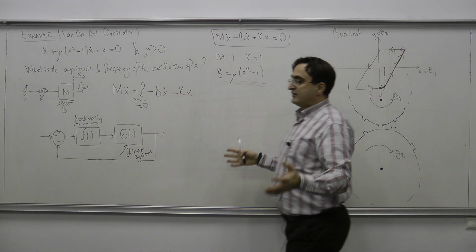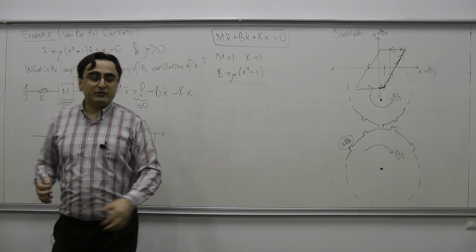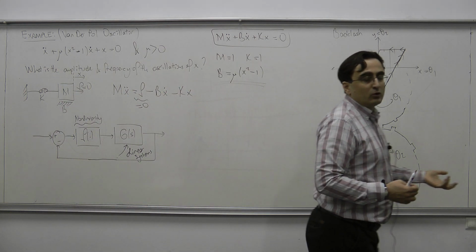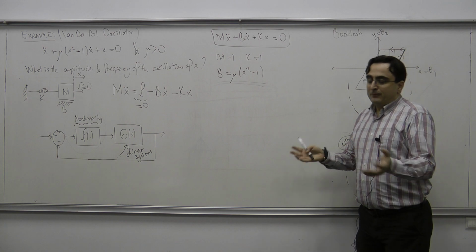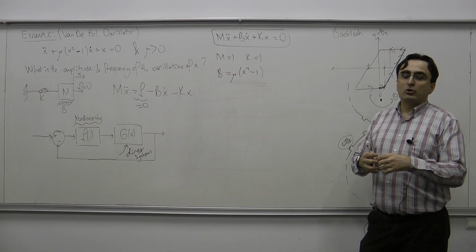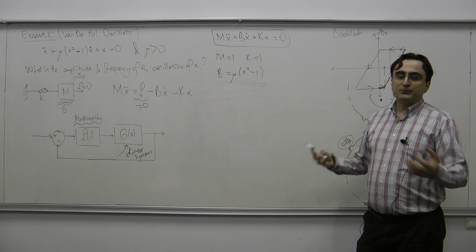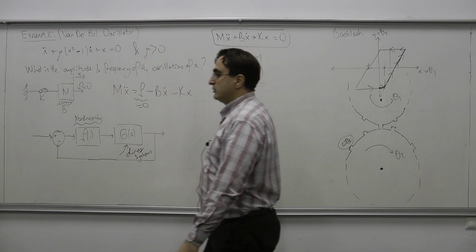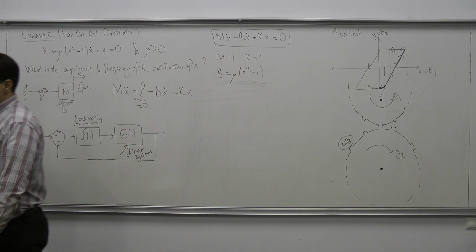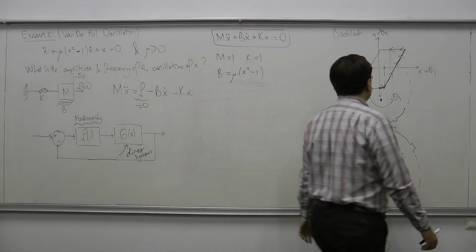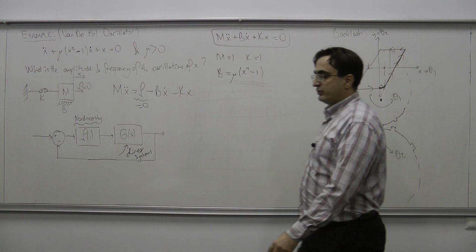And when x becomes too large, the system is going to start losing energy with positive friction coefficient. Therefore, we can intuitively say that the system is going to move back and forth between these two scenarios. So that is why this Van der Pol oscillator would actually oscillate.